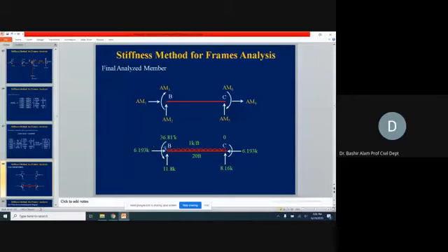Now, as a matter of fact, if you see, already we found this B joint moment and this shear and axial force when we were analyzing the member AB. So we don't need to do these calculations again. This will be just the same numbers, but in the opposite direction. And if you see, already we have the same values there. If you go to AB, at this joint B, this was downward 11.8, this was leftward 6 point, and this was counter, so this is clockwise. So here now at the right side already we found 1 kip per foot.